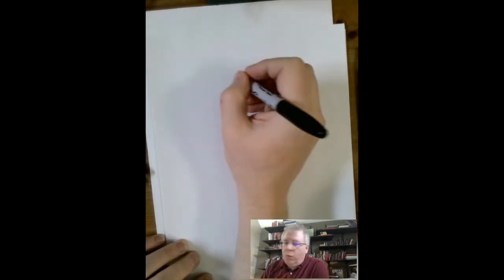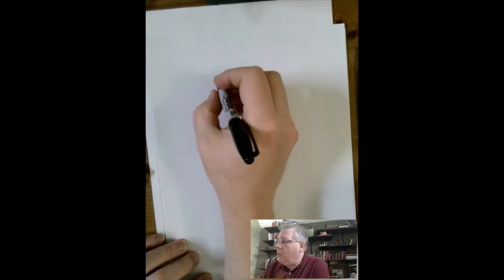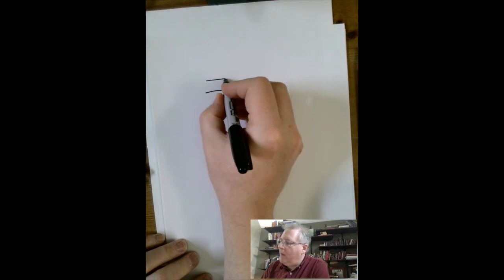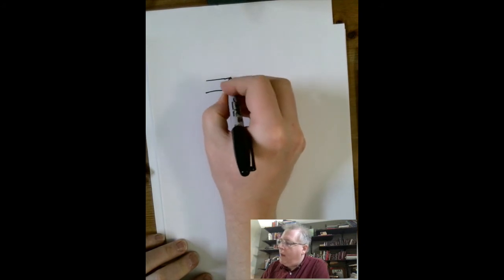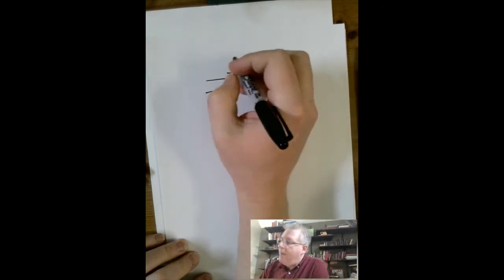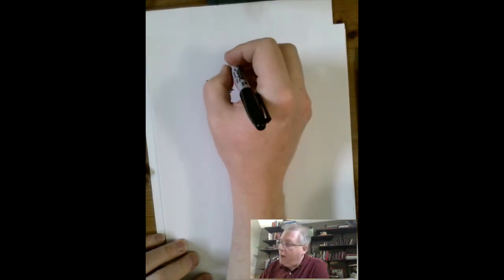Now the first type is a very easy one to understand, and so in Lab 4 I'm giving you an exercise to run through this. And we actually still use these all the time. It's called a relay. So a relay is actually a really simple device. We have two leads here. This is going to be our input. And we're going to take them and wind them around an iron core. So that makes us an electromagnet. And then we're going to have a switch up here.